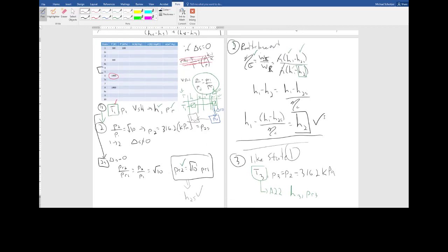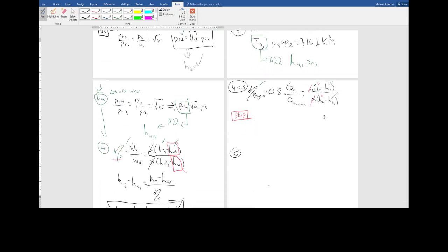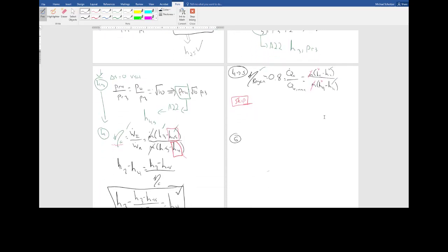So the nice thing about Brayton cycles is they will usually tell you the temperature at the top of the mountain here, right? The highest temperature. Sometimes they're a little tricky about it in that they don't say, oh, the temperature at state 6 is something. Sometimes they'll tell you the maximum temperature in the system is something, right? So then you have to know on your TS diagram where's the maximum temperature, right?